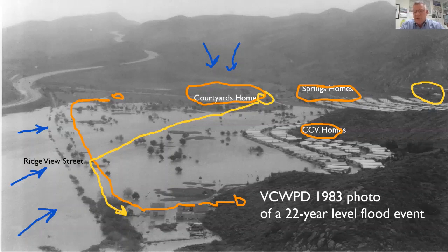That actually exceeds the 100-year rainfall, just from an intensity standpoint. That kind of flow has been addressed by the city by stabilizing that hillside. But if any of that debris were ever to get into the golf course or into the debris basin, there is more than adequate room for storage of any kind of volume like that within the debris basin before it would get into the bypass pipeline.